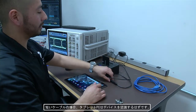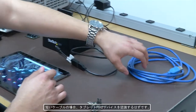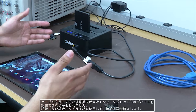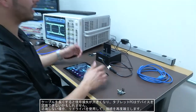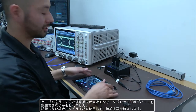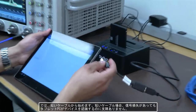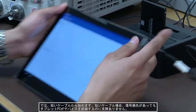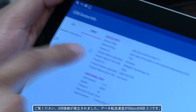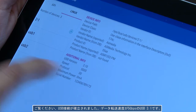I want to show that with a short cable, the tablet should recognize the device. Now when we add more cabling, more insertion losses are added to the system, and the tablet may or may not recognize it. If it does not, we will use a redriver to reestablish the link. So first I'm going to start off with a short cable. I believe the losses of the short cable should be low enough for the tablet to recognize. And there we go. We made a USB connection, USB 3.1 at a 5 gigabit per second data rate.